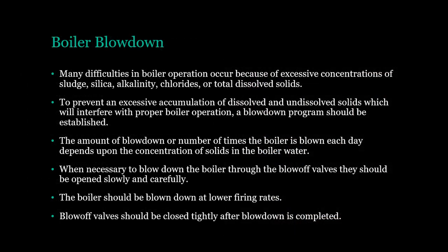Boiler blowdown. Many difficulties in boiler operation occur because of excessive concentrations of sludge, silica, alkalinity, chlorides, or total dissolved solids. To prevent an excessive accumulation of dissolved and undissolved solids which will interfere with proper boiler operation, a blowdown program should be established. The amount of blowdown, or number of times the boiler is blown each day, depends upon the concentration of solids in the boiler water.